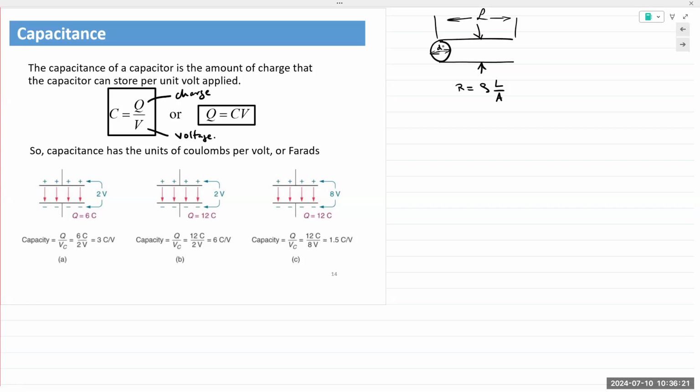So a very thin wire can carry a limited amount of current. And there are more physical equations that go into that, but that's where it comes from. And so if the current increases, that thin wire cannot dissipate that heat quickly enough. It'll just get so hot that it will blow out.